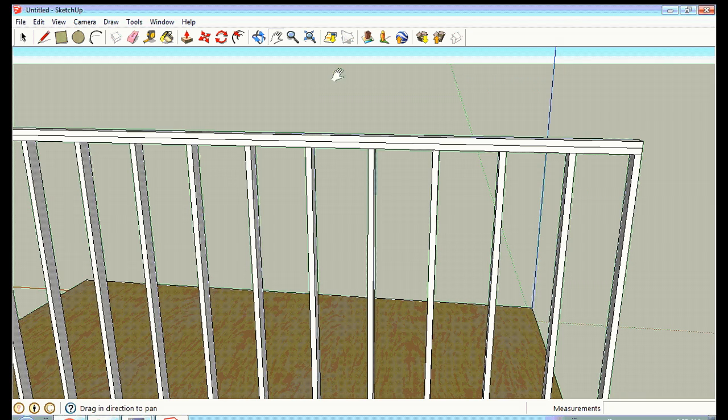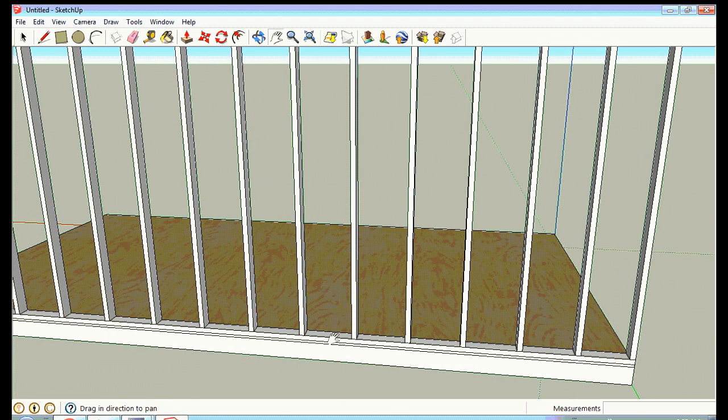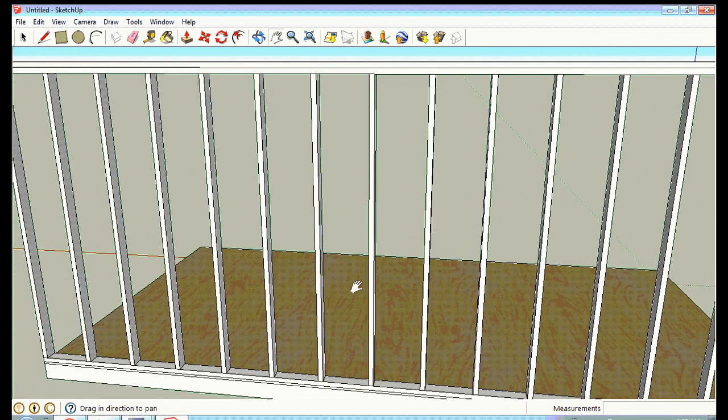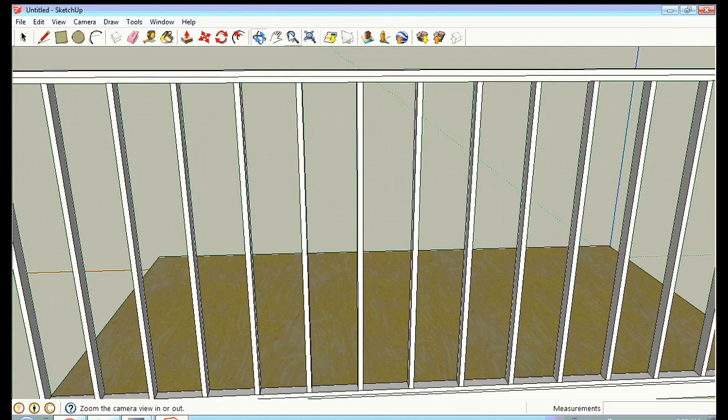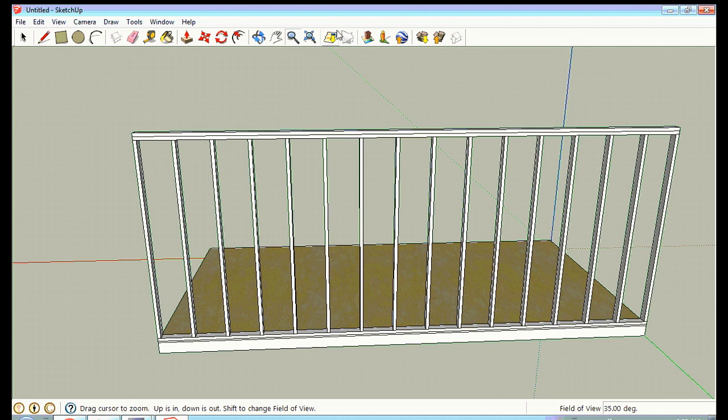So these are called the wall studs, and then it's got a bottom plate, also called the sill plate, but it's called the bottom plate, and this is just a single plate. This attaches to the ridge board through the plywood and is screwed down into your ridge board there. So there's your wall framing, okay? And I'm going to add doors and windows to this too. But before we do that, we'll go ahead and frame all of the walls.